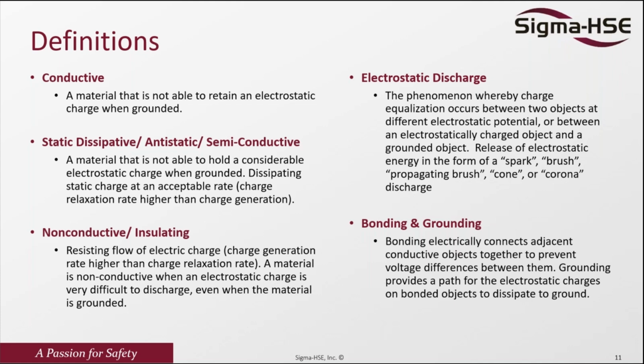So I can connect a bonding string. Then the charge will be transferred from A to B, which is a discharge operation. And if I also connect a grounding cable, from A to ground, then the charge accumulation on the conductive metal will transfer to the ground. That is a discharge, to ensure that I have equalization of electrostatic potential. So that is electrostatic discharge.